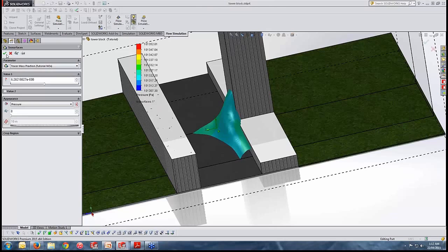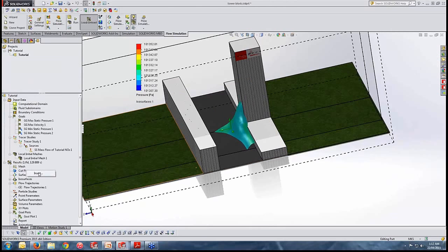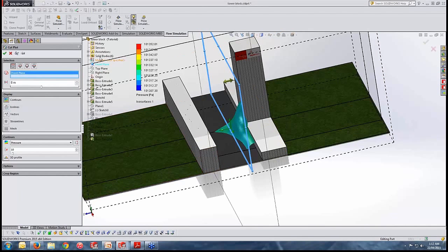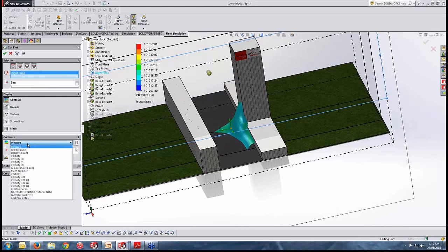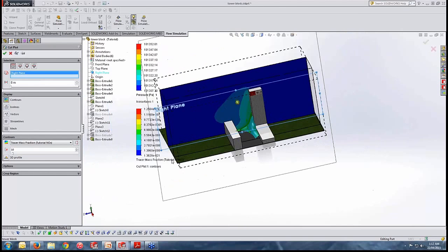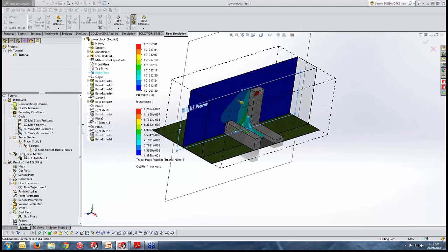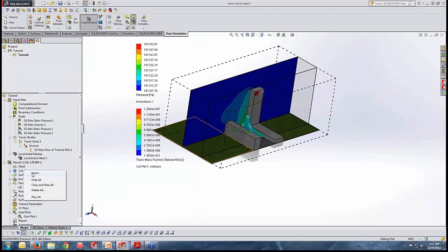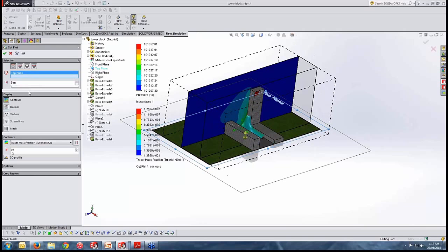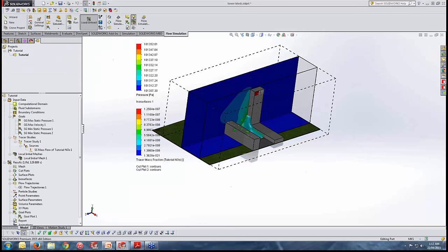You can have more and more items by making cut plots, insert, and also here making your first cut plot on, let's say, right plane, and then tracer mass fraction and show this, and also making another cut plot active here, and then this time I'm looking at top plane, tracer mass fraction of NOx, and clicking OK.